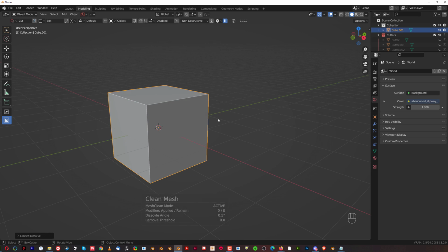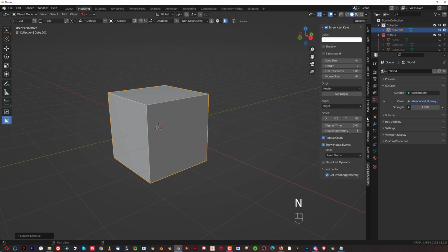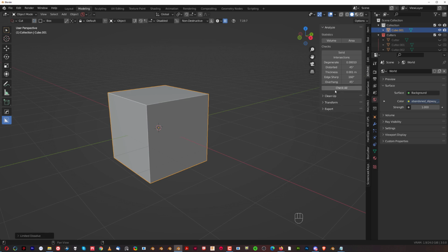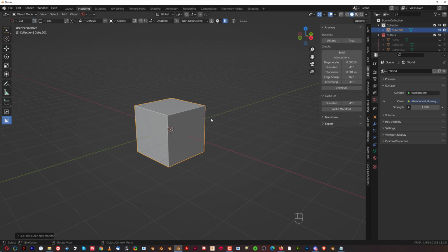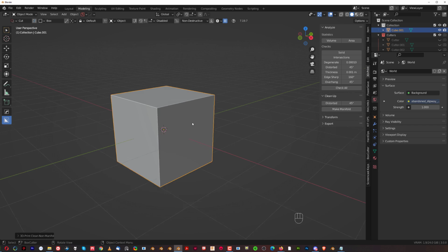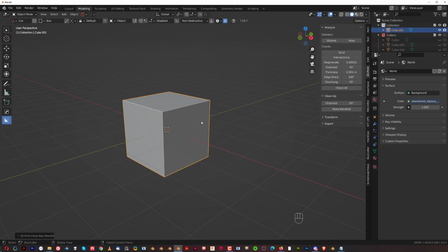And if I still need to clean it further, I'm gonna go to the 3D Print Toolbox, and I'm gonna simply go with Make Manifold. So these 3 cleaning tools are usually getting me 99.9% of stuff done automatically. I don't have to mess with faces or look for rogue geo. It just gets done very quickly. Okay, so 3 with Machine Tools, fantastic stuff.